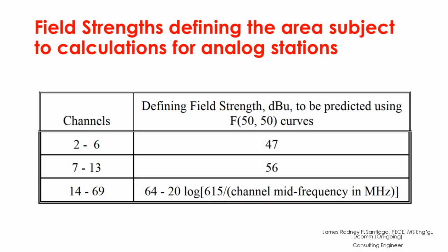The Longley-Rice methodology operates from 20 megahertz up to 20 gigahertz, as developed by Miss Anita Longley and Phil Rice in 1968. This methodology requires a computer to aid the user in generating the calculation. It's quite tedious to do manually, so the support of a computer is almost mandatory and essential to its proper use.